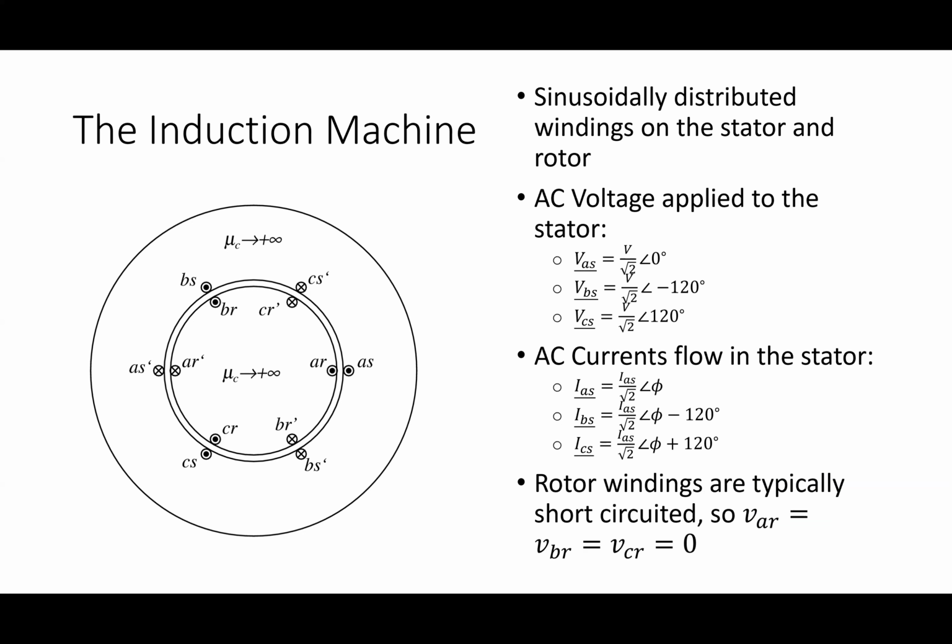And it's going to spin up until it gets to what we call synchronous speed, which is where essentially the stator field is moving at the same speed as the rotor. If the stator field and the rotor move at the same speed, effectively we said there is no current induced, right? I called that synchronous speed. If there's no current in the rotor, there can also be no torque. So that we call the no load condition, right? So up to synchronous speed basically was the no load condition.